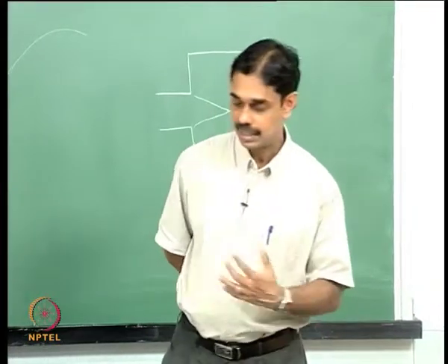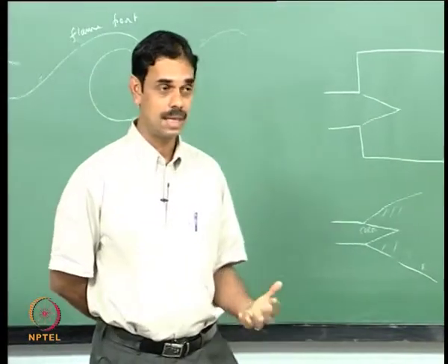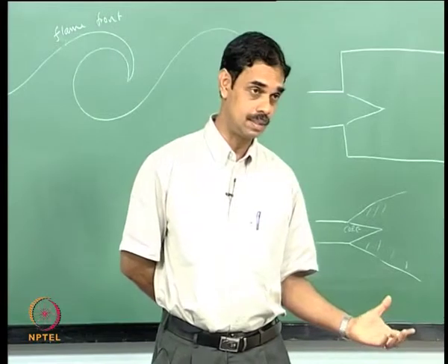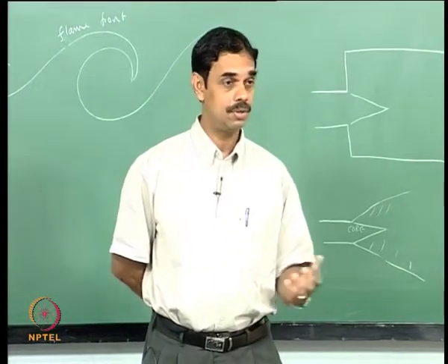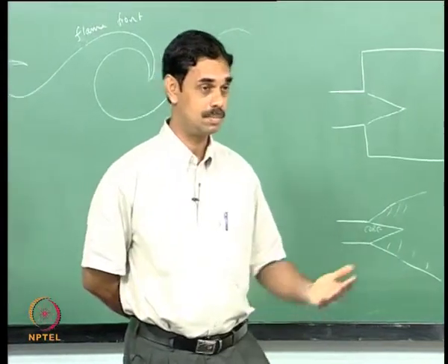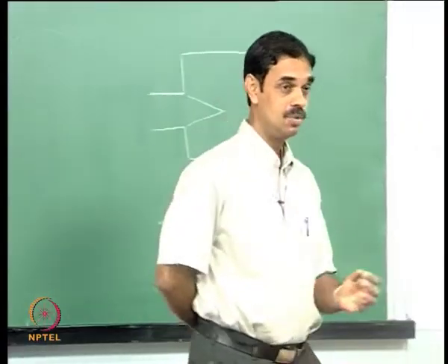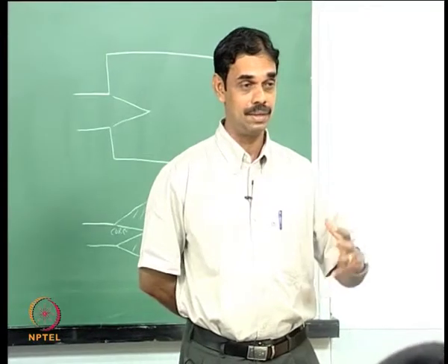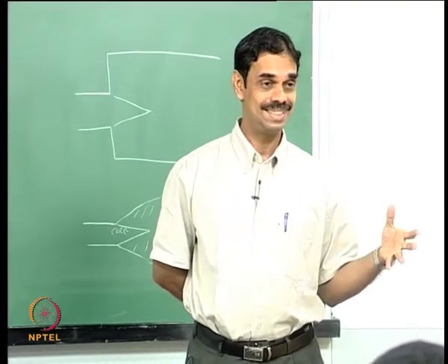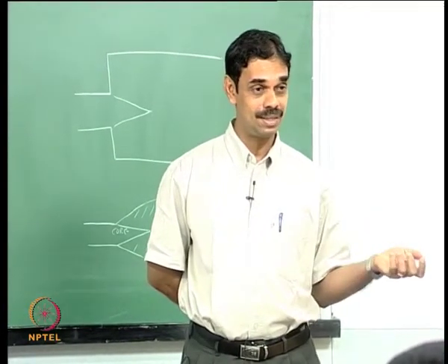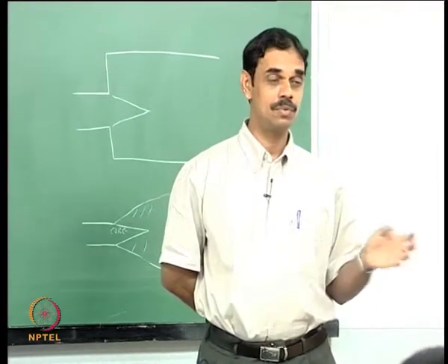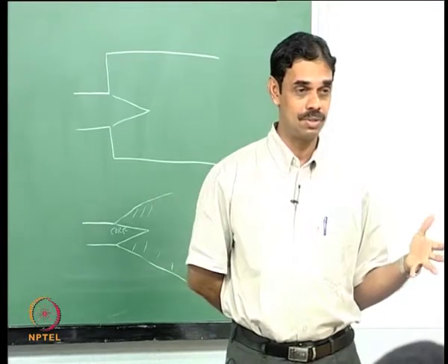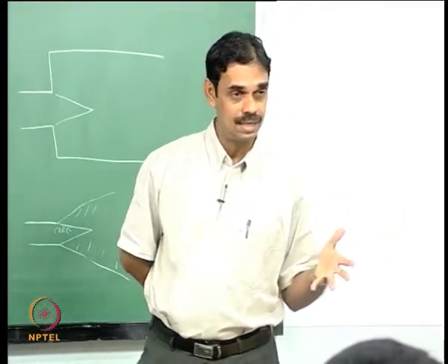Okay, you are asking whether hydrodynamic instability or coherent structures are a necessary condition for pulsating instability. No, it is not necessary at all. We showed examples, and I showed movies of a Rijke tube and also a Bunsen burner flame with a pipe around it. I didn't quite see any serious vortex related roll up, you saw wrinkles but not really, although you can set up those experiments to have them also, but it was not really necessary, we still had instability.